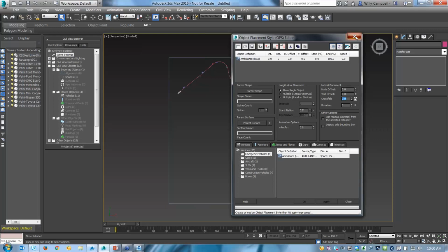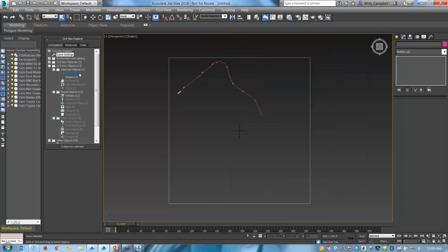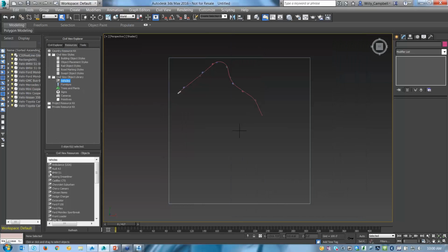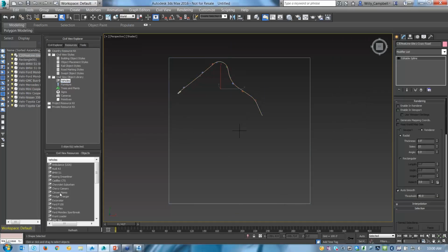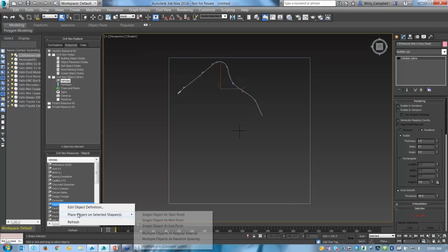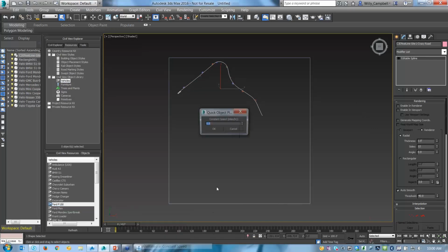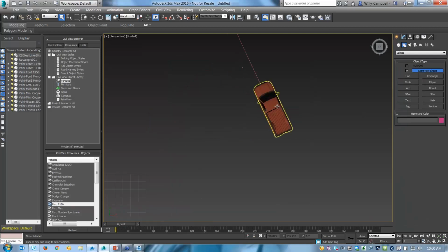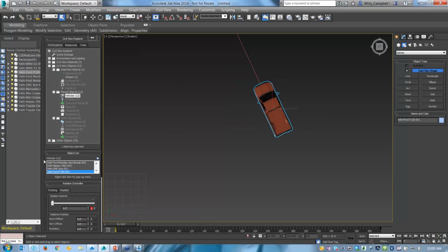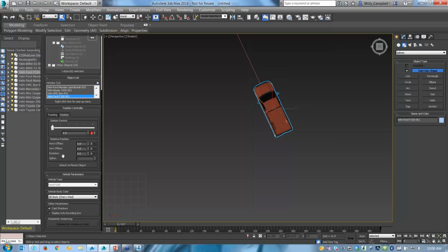Now, one thing I did notice when we were manually applying vehicles: if I pick the Ford F-150 and then go back and animate at a constant speed like we did earlier, it's going to place that vehicle right here at the beginning. I need to select it and go back to Civil Explorer, but one of the options that's not available here is the crossfall. I can change the horizontal offset, the vertical offset, and the rotation, but I cannot change the slope of that vehicle here. I would probably have to do it manually.